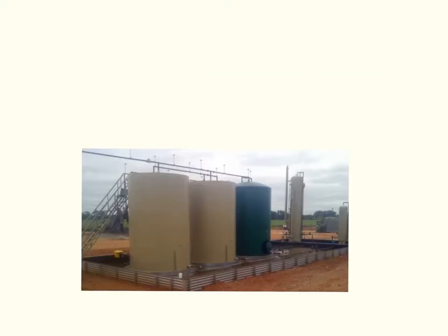A couple of areas we have to address when we look at the standard type of tanks that don't have a floating roof, so this is the fixed type, is we have to again look at the vent opening. And we don't have a great picture here, but hopefully you can see the very top of it. And so once again we look at the very top, and we have a sphere, and that sphere, of course, is our Zone 1 location.